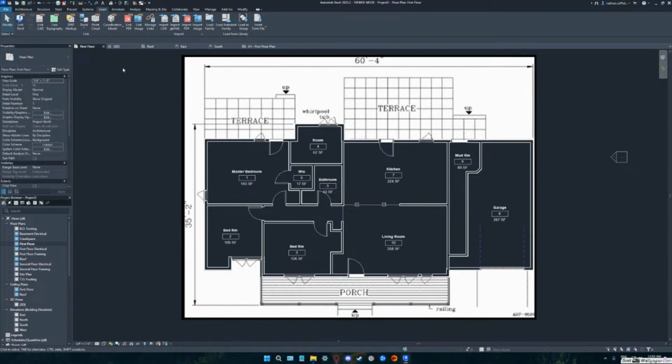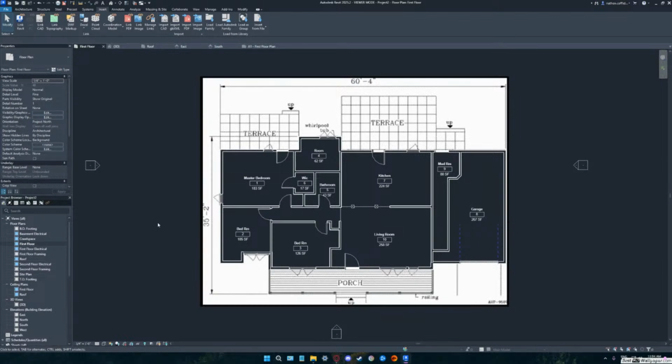All right, so you got Revit links, and we are going to work a lot with Revit links, because of the way the template is set up. If you look at yours, it has first floor electrical, first floor framing. I don't recommend that you put all those disciplines into one file. I think it was even worse with the template that you had used yesterday. I think it even had the plumbing and the mechanical. So it's sort of ironic. Revit, Autodesk, once again, starts you out in the wrong direction. What I'm trying to tell you is that first button on there, Revit link. Typically, what I would recommend is you build all the architecture in one file. You build all the plumbing in one file. You build all the mechanical in one file. And what you do is you link those files together.